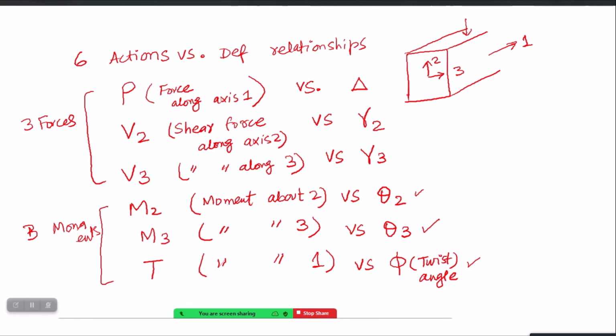For example, when you say that your material has an elastic Young's modulus which is constant forever, defined by E, and then when you say that your cross section shape has a particular width and depth, the program can calculate the second moment of area or moment of inertia. So EI will become the flexural stiffness, which can be combined with the length of the element to make a constant slope for the moment versus rotation behavior, and that will remain constant forever.